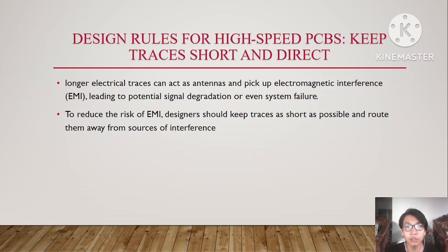One of the design rules for high-speed PCB is we keep our traces short and direct. The longer electrical traces can act as antenna and pick up electromagnetic interference, EMI, which leads to a potential signal degradation or even system failure.